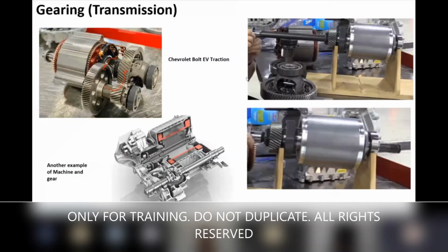For the gear, one example here is from the Bolt, which is again available on the net. You can see this is the rotor, and there are magnets inside, and you can see how the final FDR, that we call final drive ratio, is getting calculated, and how it is connected. It is much simpler than a hybrid, isn't it? Hybrids will have a lot of other elements like DCT and other gearing and long transmission. But here it's becoming simple, with very few rotating parts compared to even a hybrid or an IC vehicle. And that also helps in efficiency, isn't it?